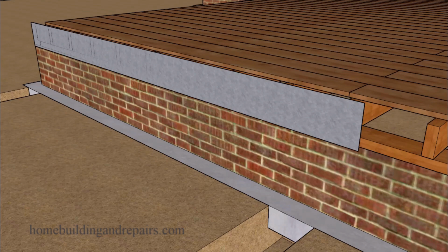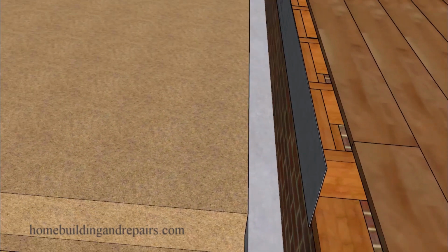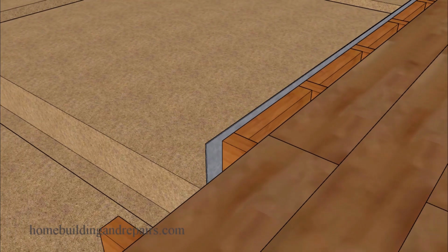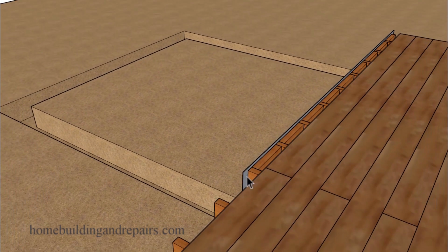Just make sure that the sheet metal is installed before you pour the concrete. And make sure that the sheet metal isn't sticking up. I've actually made this mistake before and had to bend it over, and it won't be too bad for carpeting or other flooring. However, it could be a nightmare for the workers to walk across and trip over. And of course, that's the reason why I'm pointing it out. You might want to just lower it a little bit just to make sure that it isn't going to be sticking up. And after you remove the wall, you can add a furring strip here.